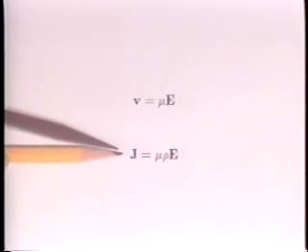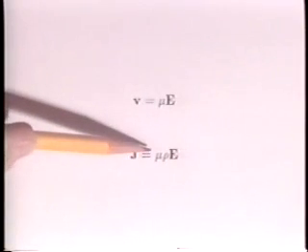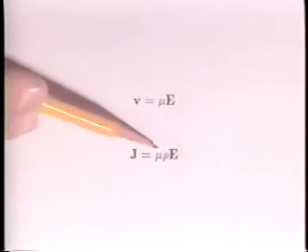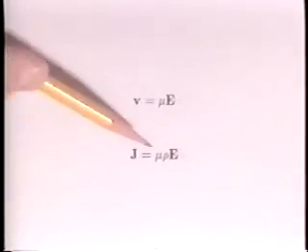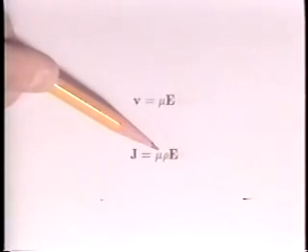If these particles are the only ones that are charged and moving, the current density is the product of their velocity and the charge density rho. The product of mu and rho is an effective conductivity. Unlike the conductivity associated with an ohmic model, this conductivity is a function of a variable that is itself as much a function of space as the potential.